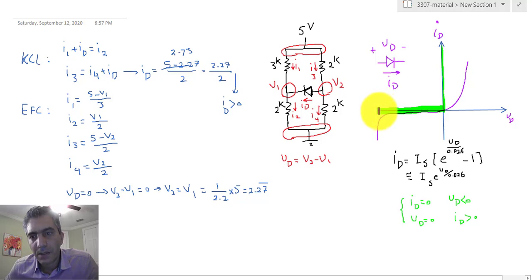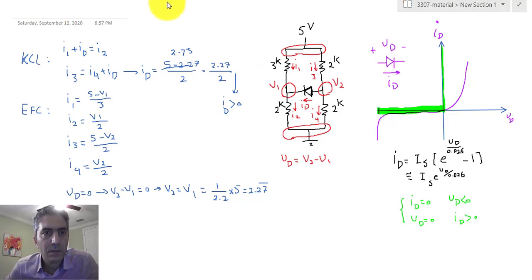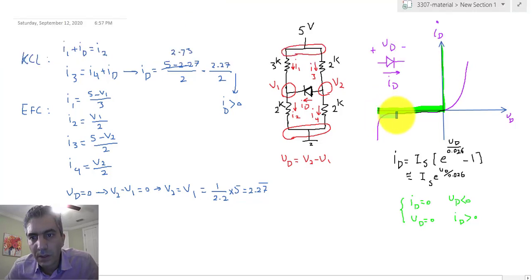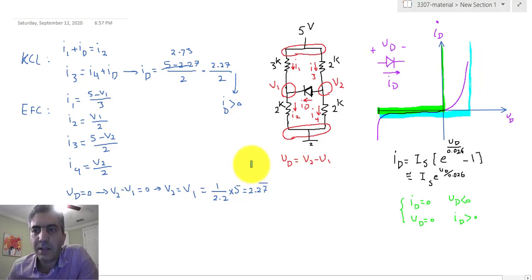And in this one, I'm going to use a different color now. Blue. So the blue one assumes that for any negative value of the voltage, the current is 0, but then extends all the way to what we call the built-in voltage of the diode, and then assumes that the diode turns on and turns into a short circuit basically at that point. So you can see, well, we're not really ignoring this offset in this new approximation.